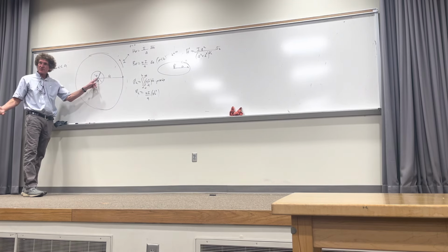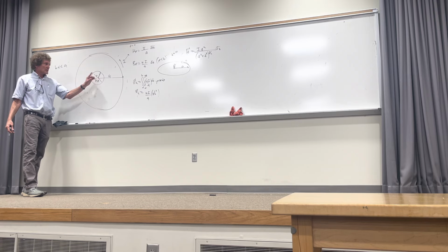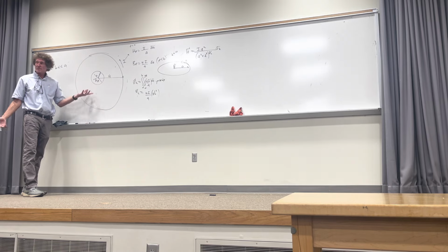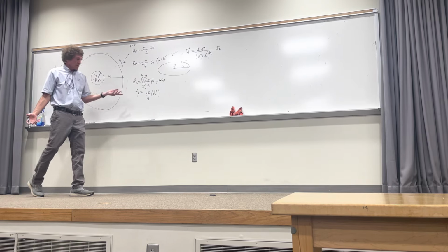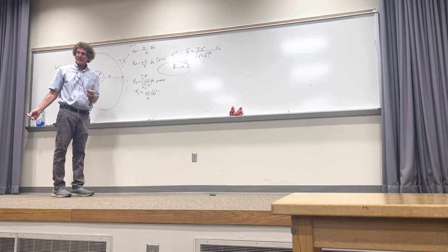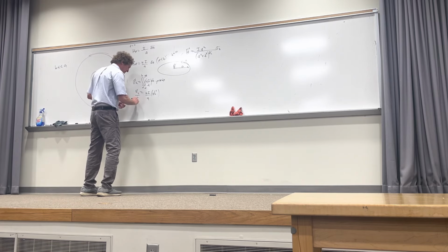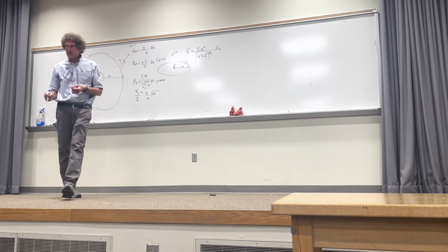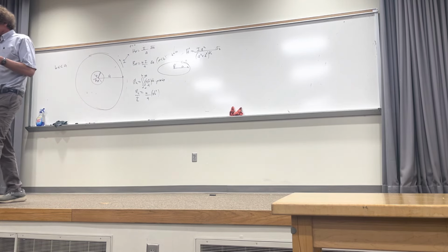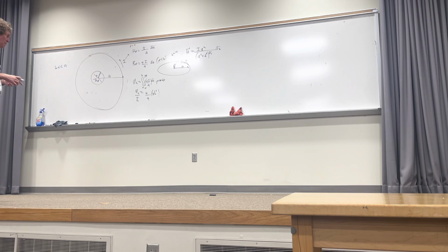If we assume the H field's constant, we get the B field by multiplying by mu, and then we integrate it over that surface. Since the H field is assumed constant, for the B field we just multiply by the surface area. Y'all with me? What's the last step? If that's the magnetic flux that links them, to get the inductance, just divide by I. That is the problem I gave you, and that would be the inductance between the inner and outer loops, the mutual inductance.